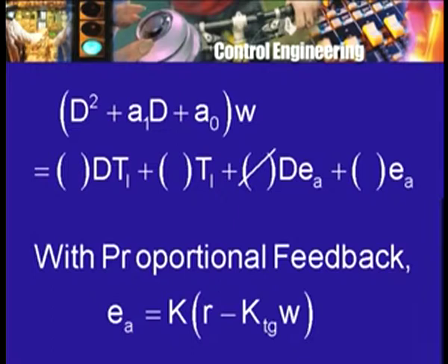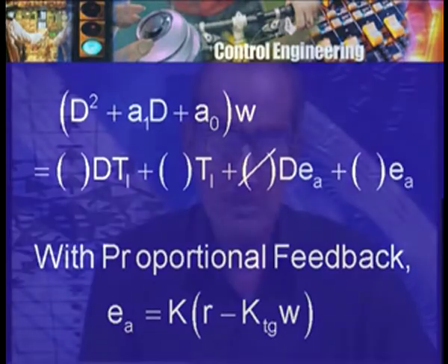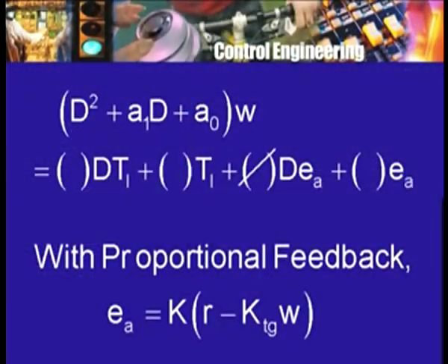Now, what is happening is that because of this proportional feedback, we are changing this coefficient A0 of the characteristic polynomial. By changing A0, of course, the roots will change, and therefore, one can find out the effect of this change. This is the kind of thing for which the root locus method is appropriate. In this case the polynomial is only a quadratic, so one can write down an explicit formula for the roots of this polynomial and see the effect of this gain coefficient k on the nature of the roots.